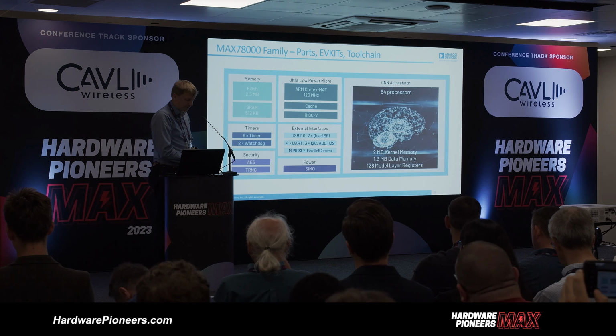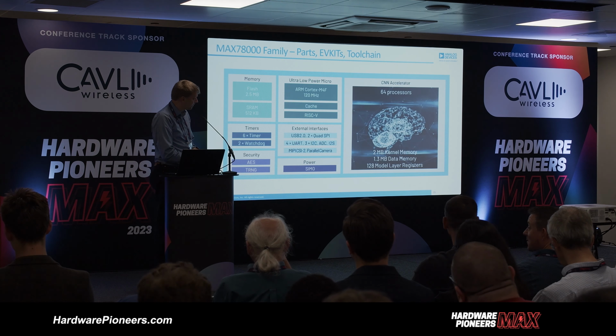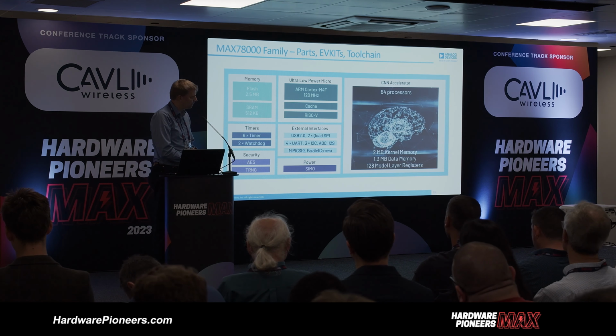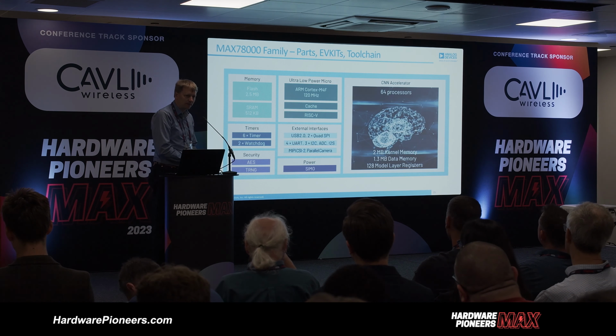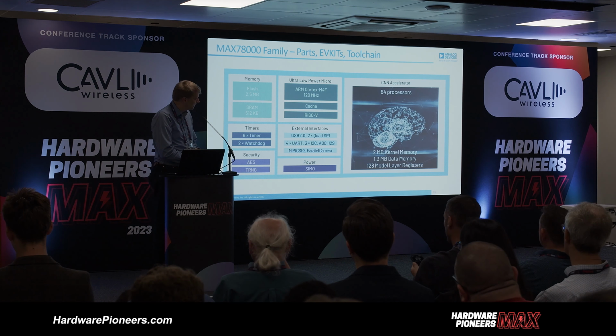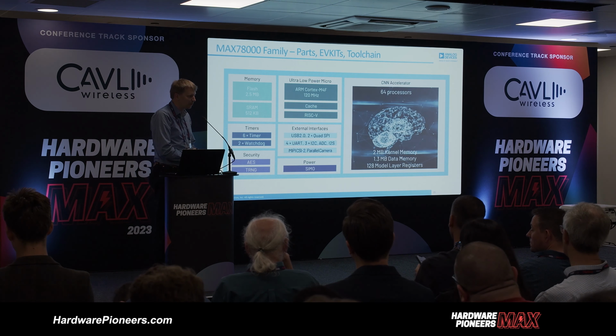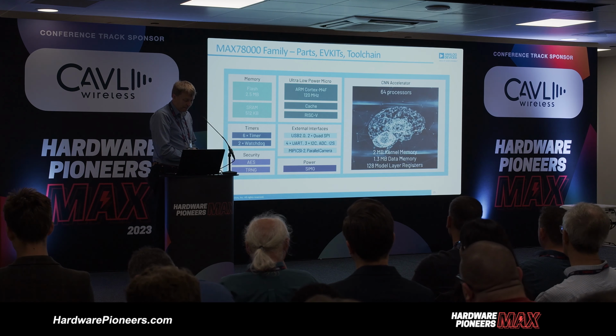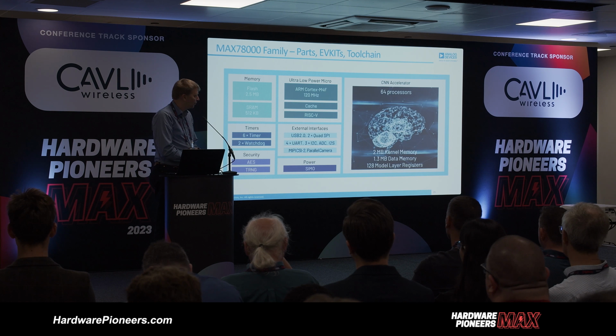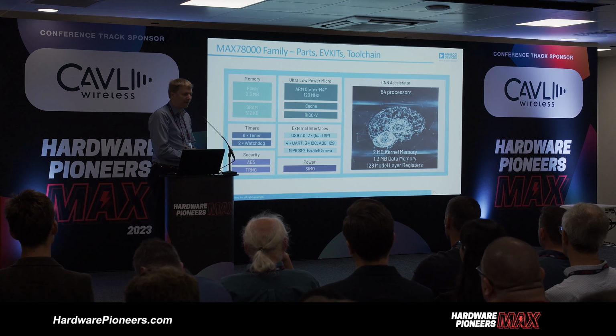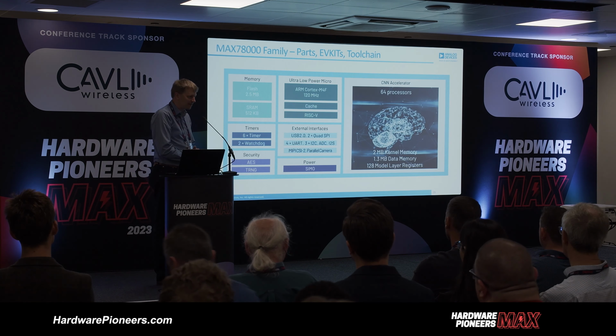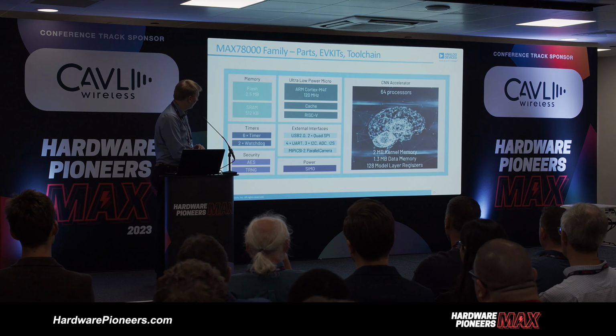And the magic starts here on the right-hand side. This is our own IP, which we developed a couple of years ago. It's actually a CNN accelerator using 64 processing nodes in parallel. And the trick is to not move data, specifically the kernel memories as well as the weights and biases, around from the external flash.